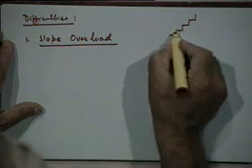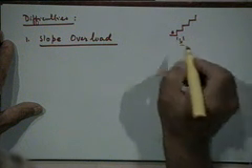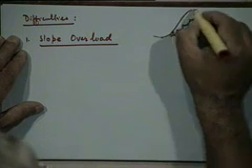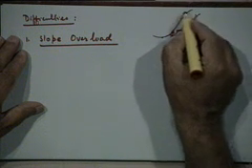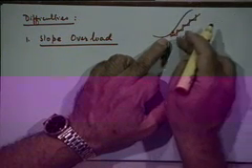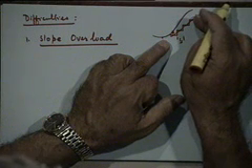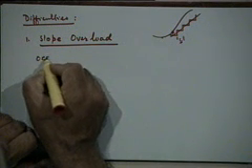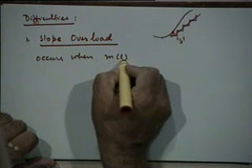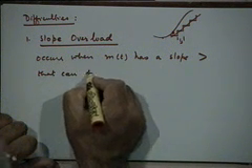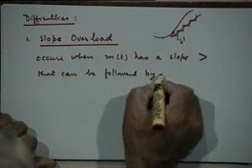You cannot have a staircase faster than this, right, which is dictated by two quantities. One is the step size s, the other is the sampling interval ts. So that is the maximum rate at which your signal can be allowed to rise. If your signal happens to rise suddenly like that, right, you will not be able to track this sudden change in the signal, right? So if during any time interval the slope of your signal increases beyond the maximum slope that the staircase can take, right, there will be the so-called slope overload effect, right? So this occurs when m(t) has a slope which is greater than what can be followed by a staircase approximation.